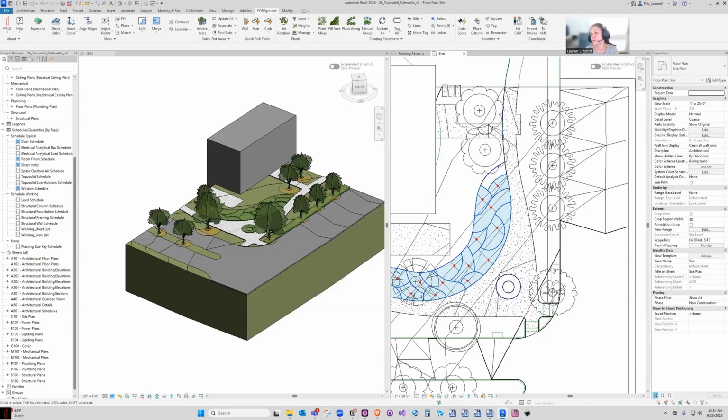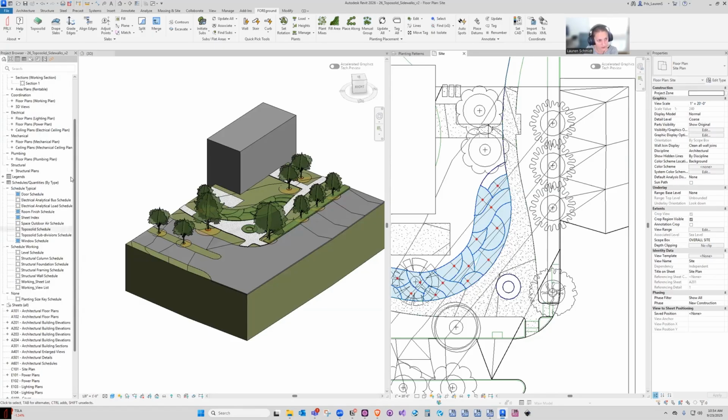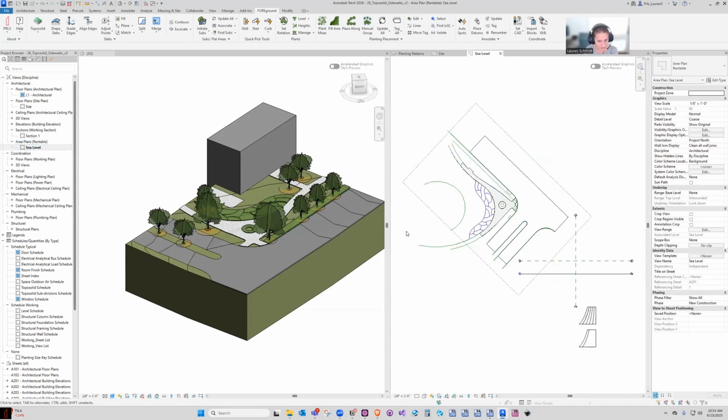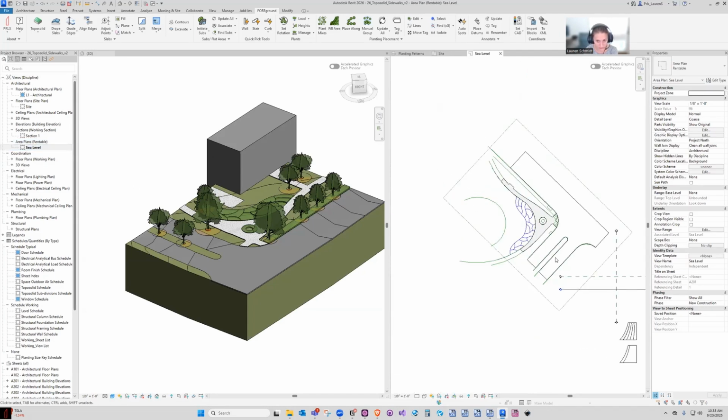Yes. So rooms versus areas, is one of those things that I started out using areas and have switched to using rooms. I will say rooms have their downsides over areas. The main downside to areas is that area plans don't have full functionality in the Revit environment. I have an area plan in this file just to show.